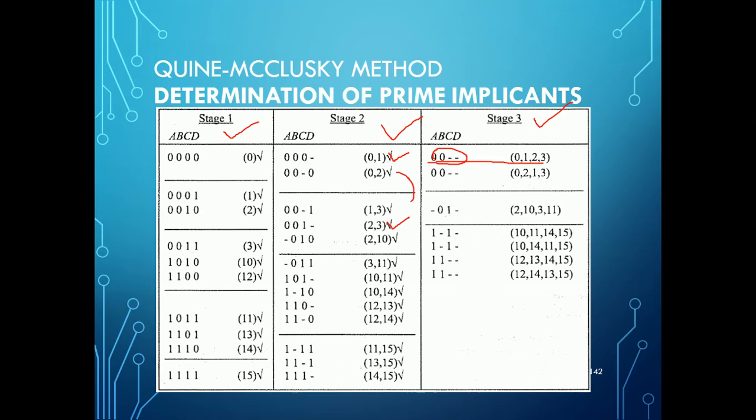Now the next term is 0 2. Again you have to see whether you can combine it with the very next adjacent term. So 0 0 is matching with 0 0 of this 0 1, that you can represent with dash. This dash is also matching with this 1 3 dash. So that's why write it as 0 0 dash dash. Done. Which two terms are getting checked now? You have to check mark 0 2 with 1 3. So that's done.